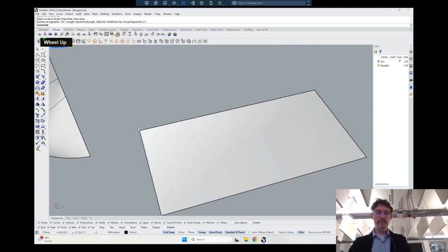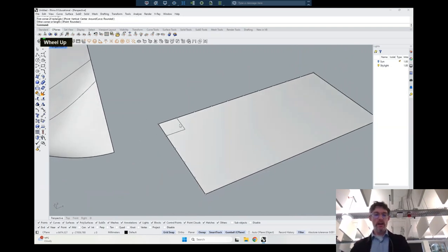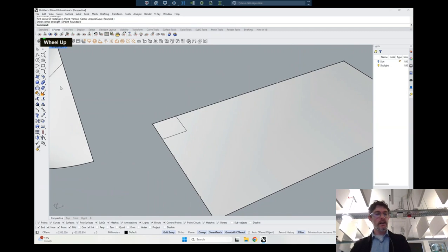So now what I have is this equally spaced grid. And what I can do is draw a rectangle that hits that point there and this point here. Oh, I just need to turn off my center snap because that's messing everything up. This point here and that point there. And so it's lining up. You see it's got those little gray snapping lines lining up with that. And now what I have is the guide rails for an interesting little surface.